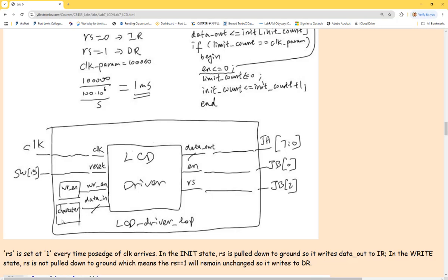You can see in here, all these character bytes are being put into registers. You actually write it into your Verilog, and eventually they will be interfaced with your LCD driver and sent as characters or bytes to the LCD driver, and eventually arrive at the JA ports, which is shorted to the LCD's data pins.